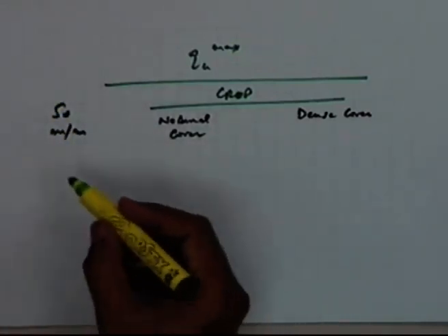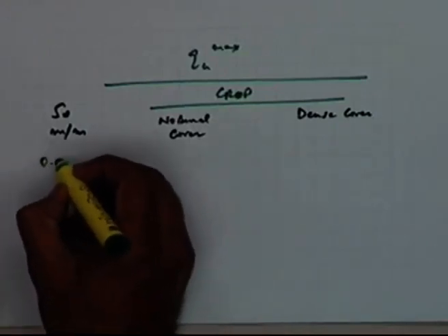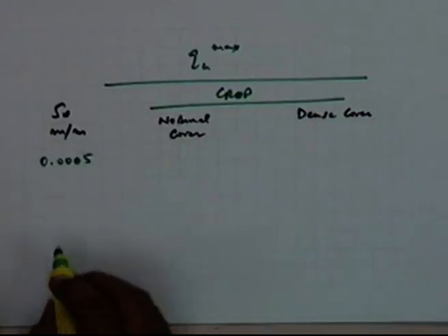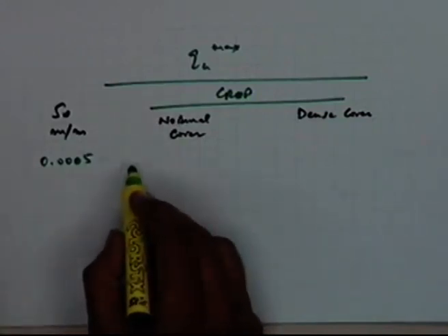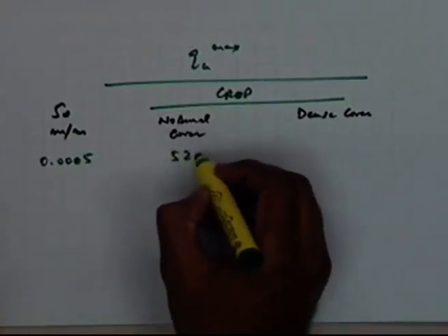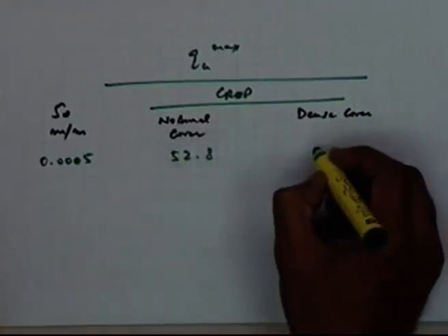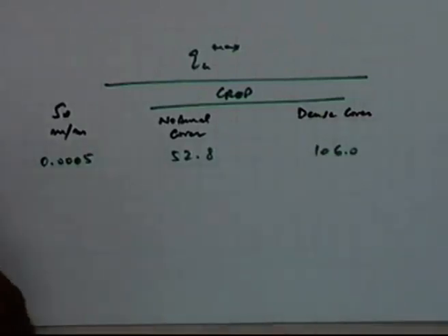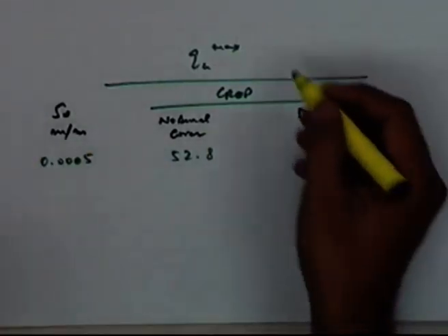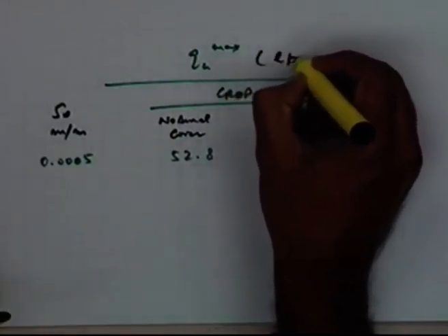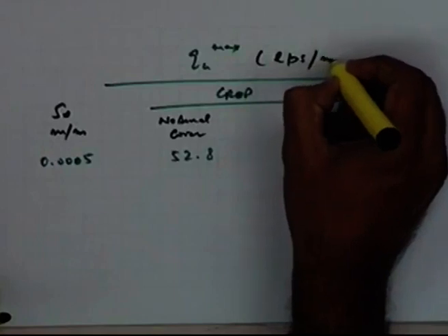let's have a look at some values. Maybe if this is the slope 0.05%, you can afford to use a high stream size. Now, this stream size is not in meter square per second, this is in liters per second per meter width of the border.